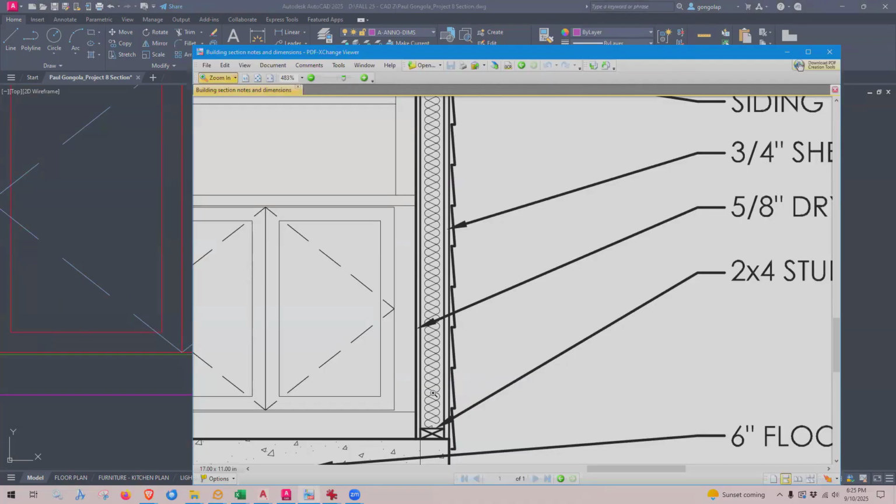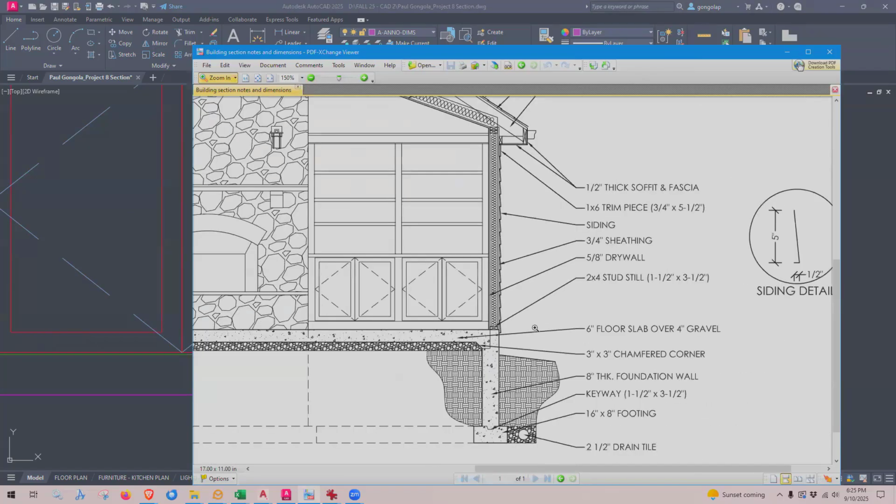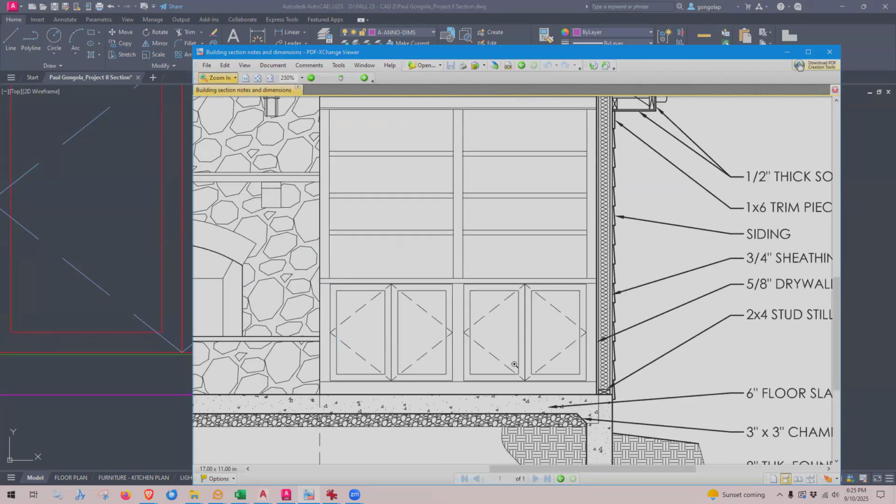I'm showing these lines pretty heavy here, and notice that I'm talking about line weight now. Notice that the interior lines are quite light, and that's our extra light layer that we put them on. And then the construction lines over here are heavier. The heaviest lines on our building section are the inside edge of the wall and the outside edge of the wall.